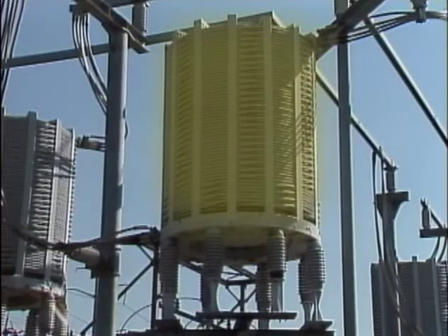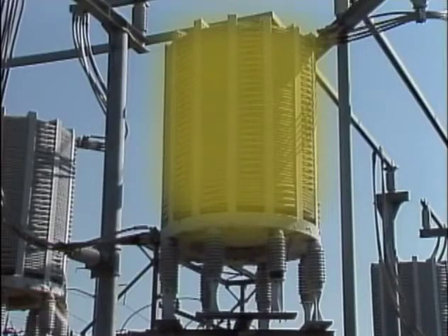As source current to the reactor increases, induction in the coils increases, further inhibiting current flow through the reactor. Now, during normal system conditions, the current flow that is inhibited by the reactor is minimal. Where the reactor comes into play is when current increases rapidly, for example, because of a fault in the system, or switching surges, or surges caused by lightning strikes. In cases like these, a series reactor is quite effective at limiting current flow.